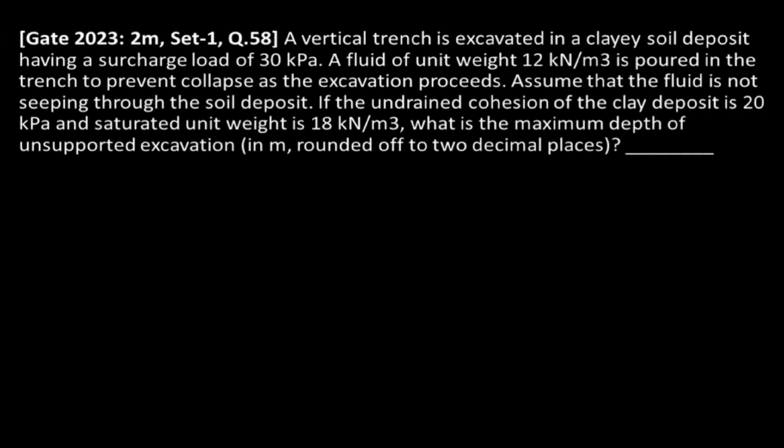In this question, they have given that a vertical trench is to be excavated in a clay soil deposit which is having a surcharge load of 30 kilopascal. They have also said that a fluid of 12 kilonewton per meter cube unit weight is poured into the trench to prevent the collapse as excavation proceeds. Right. And they said that the fluid is not seeping through the soil deposit. Right. So they have given the parameters of the clay and they're asking us to find out the maximum depth of